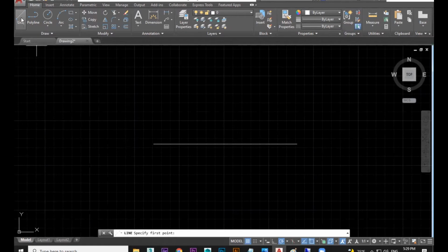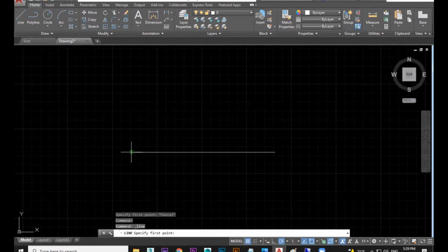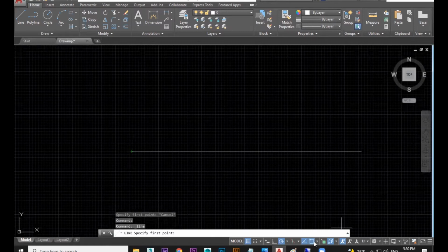See what happened. I take a line tool again, go here and snap it. Okay, if the snap is not coming, you need to switch on from here. Okay, so snap here, then move your mouse up. You see 15-degree, it is snapping. A green color line will snap your mouse. That means this is my 15.